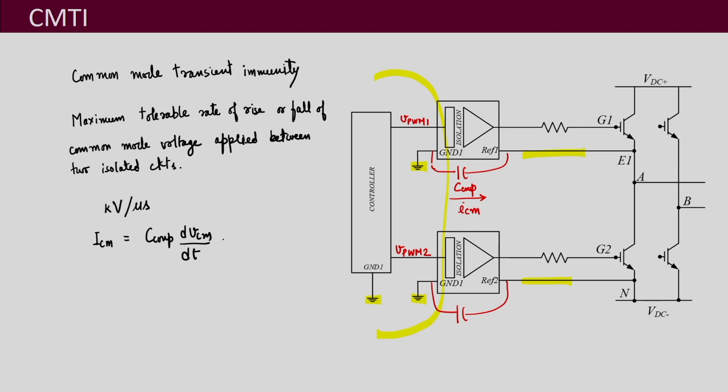This is what it is, and so this part of it, this dVcm by dt, whatever it can withstand, that is specified as the CMTI.